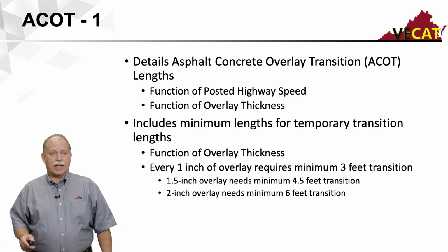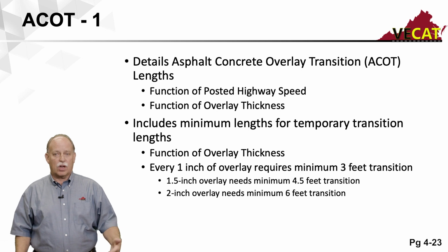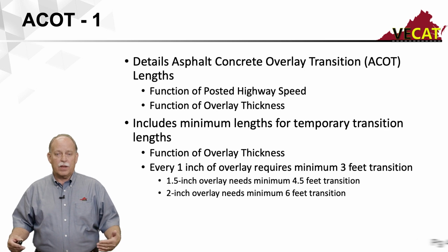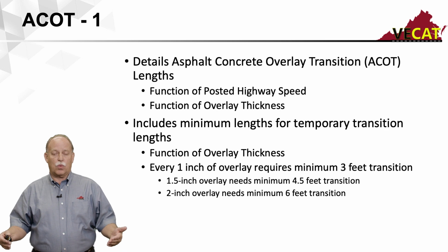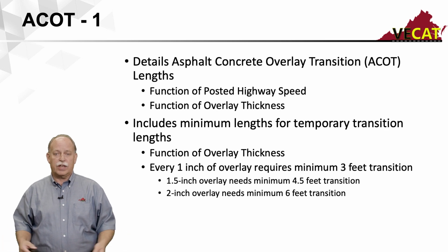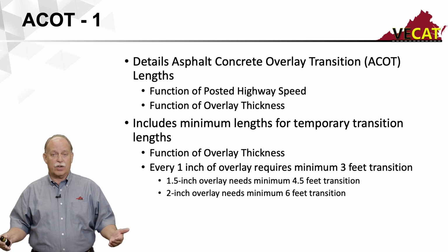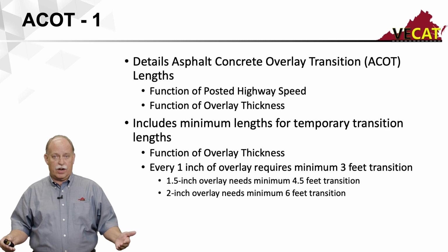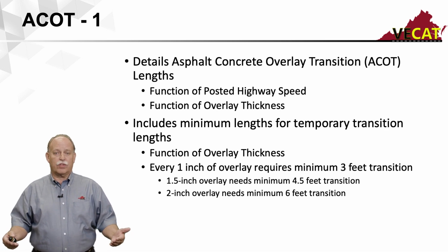I talked to you about ACOT 1. What does ACOT stand for? ACOT stands for Asphalt Concrete Overlay Transition. That is something that was developed a number of years ago, primarily because of our bridge structures. When ACOT 1 was developed, one of the concerns that VDOT had was they're not allowed, or they don't want to, reduce the clearance that's under any of the bridges. They try to maintain whatever clearance is there for all of their bridge structures. So ACOT 1 was developed to work with that.